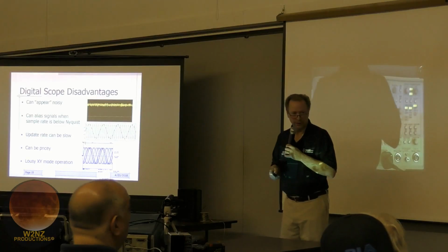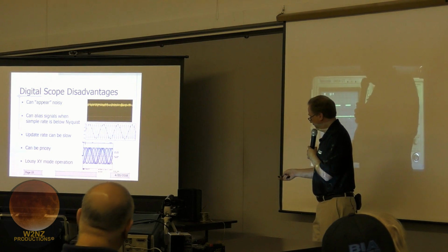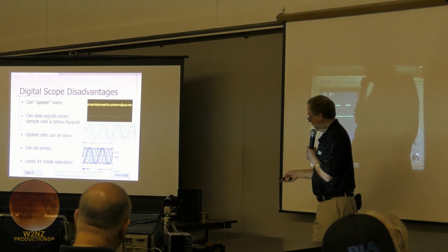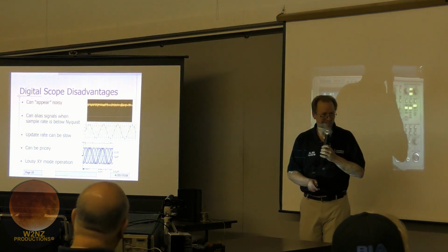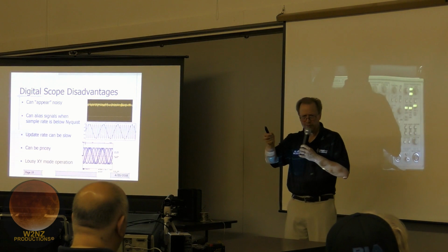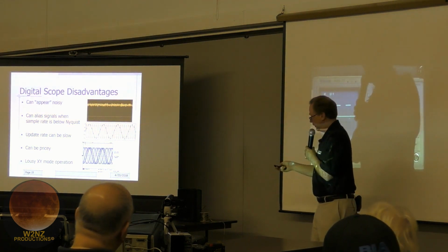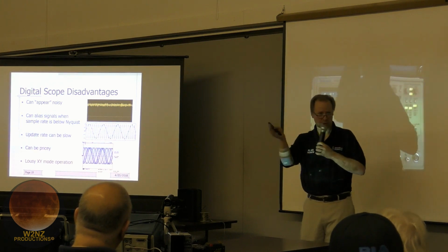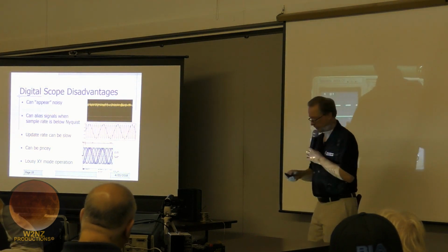Thank you. What's the bottom graphic on that? Well, this bottom one down here. Yeah, that. So this is what a waveform would look like if you were aliasing it. I thought so. Yeah, because you might say, hey, I'm triggered, but the signal's moving all back and forth because you're doing that undersampling. And so it looks like this randomly moving, untriggered type thing, even though you really are triggered. Okay.